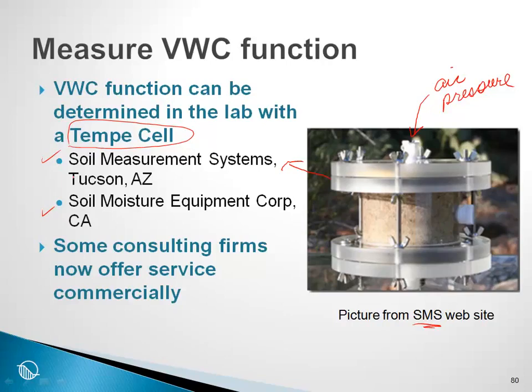So it is possible to measure the volumetric water content function, but this is something that is only done once a lot of preliminary analyses have been done and it's proven that the volumetric water content function for that particular site or conditions needs to be defined with considerable care. So this is possible. Let me repeat, though, that measuring the conductivity function is seldom, if ever, done.